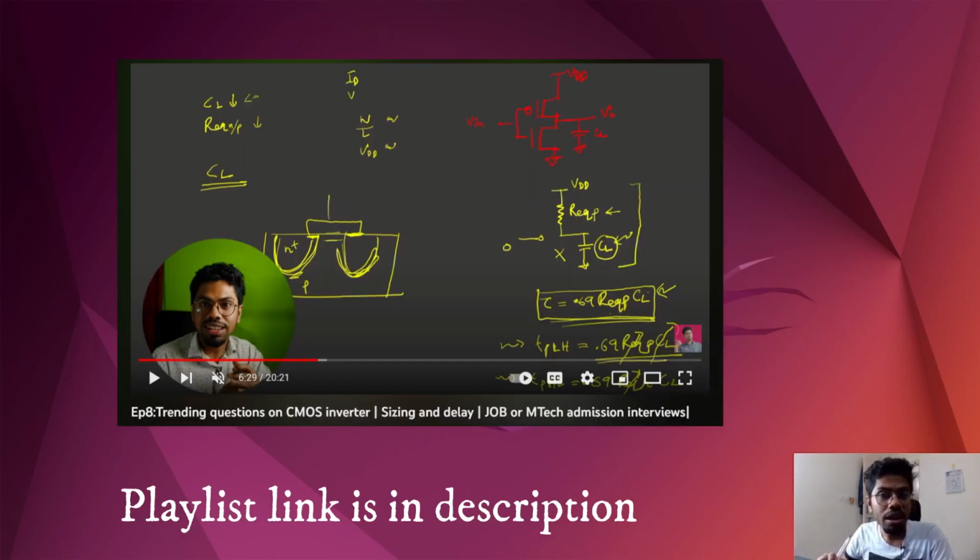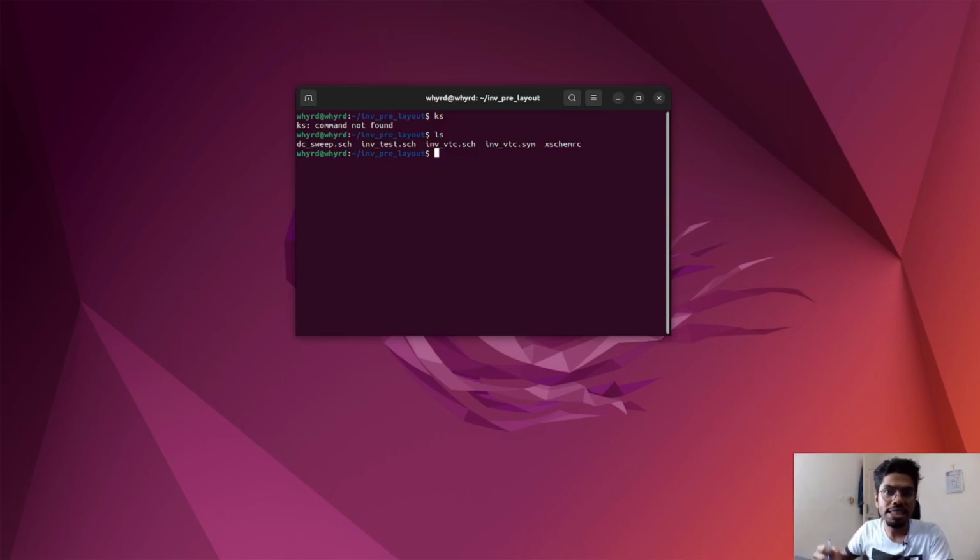And if you remember our lecture 8 of the interview preparation series, there we gave a few ideas by which, as a designer, we can reduce the delay. There are mainly three ways. First, reduce the power supply. There are cons and pros, we will see. Second was increase the size of your inverter, your design. The con is obvious, we need more silicon area.